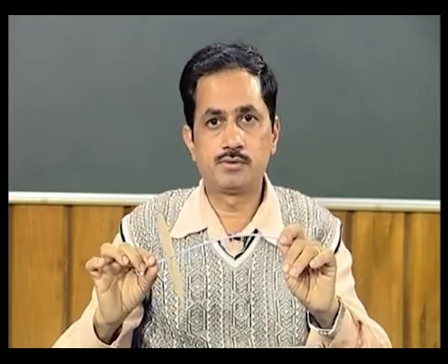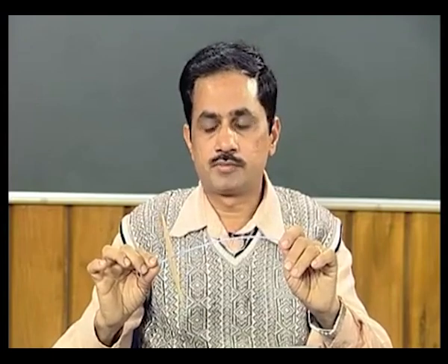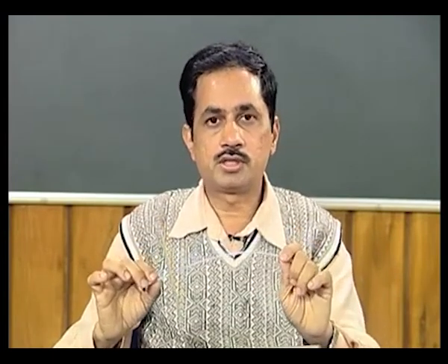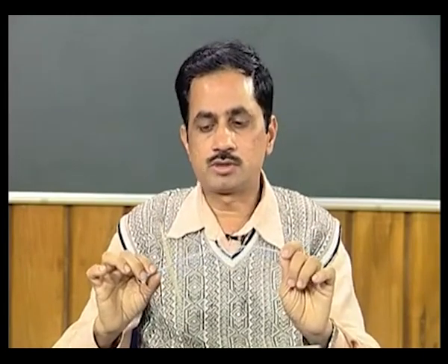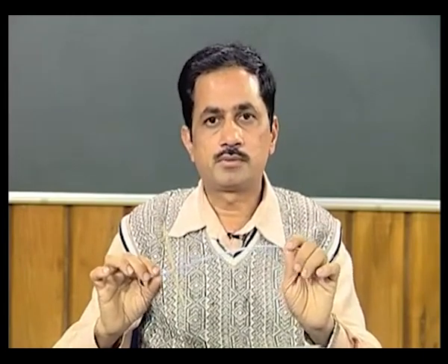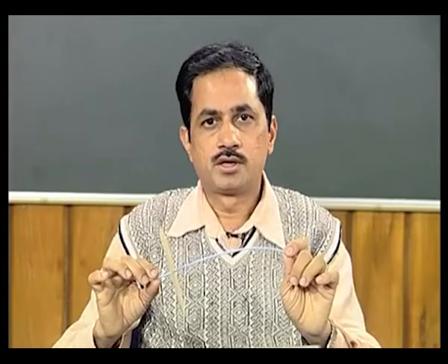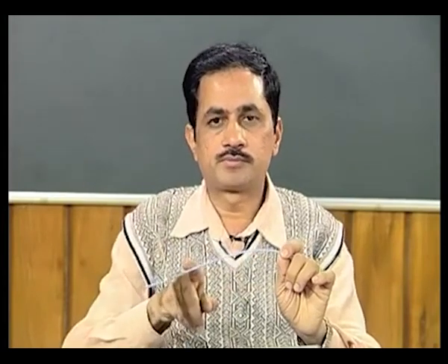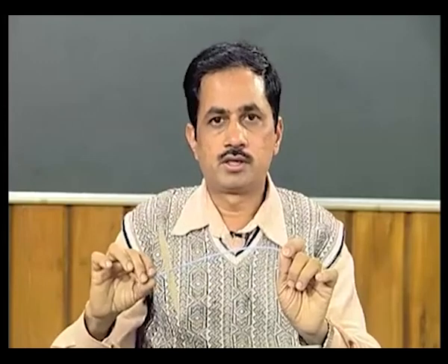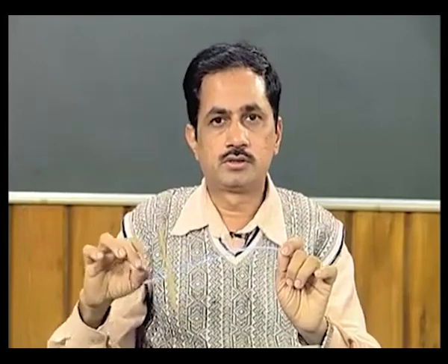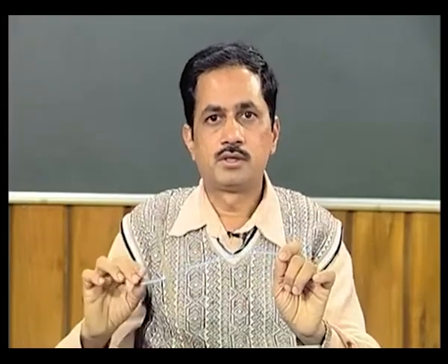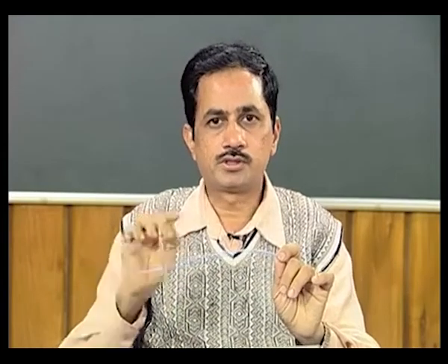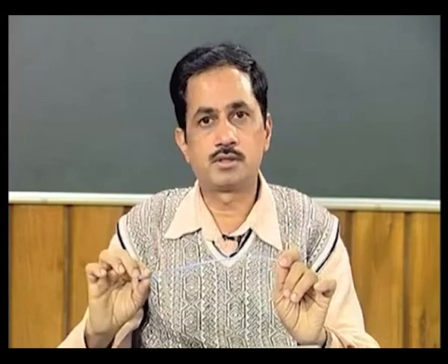So this will be a free vibration analysis, and synchronous motion is not there. In the previous case we considered it, and we saw that when the shaft bends and whirls in synchronous condition, the fibers of the shaft which are in tension always remain in tension, and those in compression remain in compression.